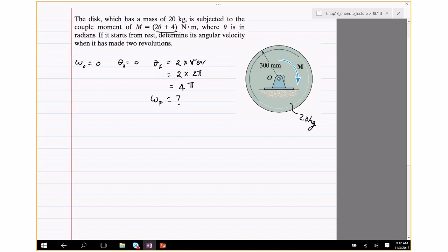Here's something I recommend: always draw a free body diagram, because we always give you credit for free body diagrams. It is not okay to draw it like this. This is not a free body diagram because the body is not free there. You're just showing the forces. You cannot show OX and OY when it's already connected to the pin joint.